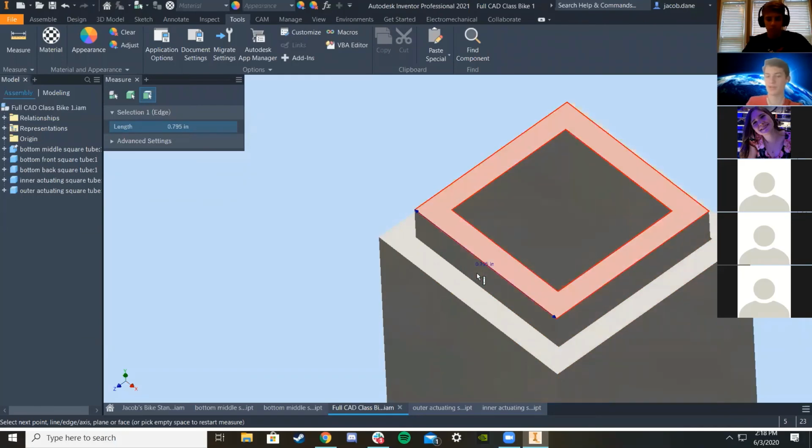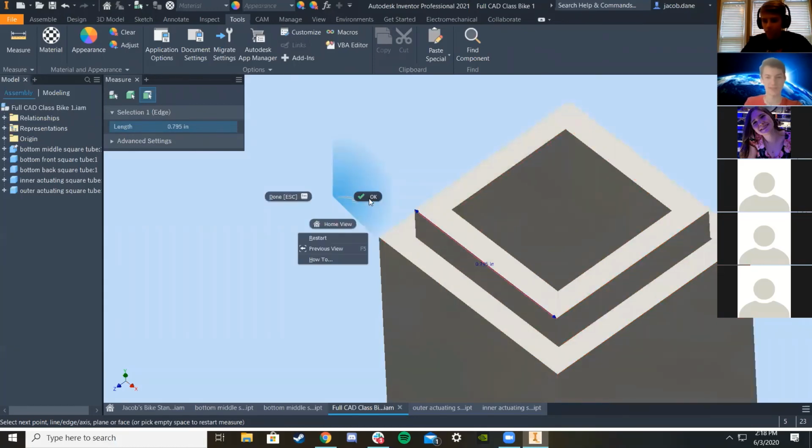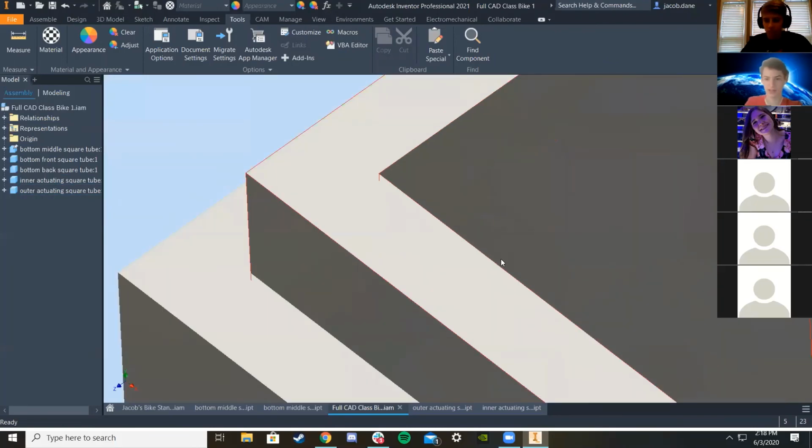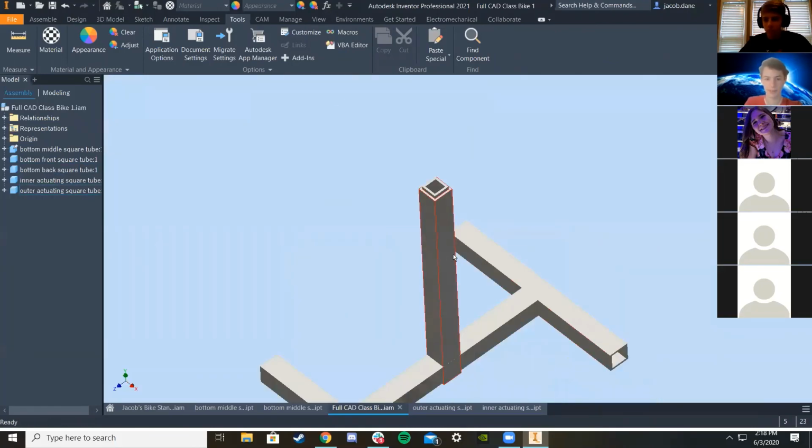But what Jonathan reminded me of is that because the whole thing has a tolerance of 0.05, it's actually half of that on one side, because the tolerance is divided by both sides. Does that make sense?